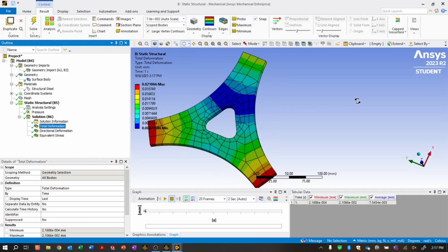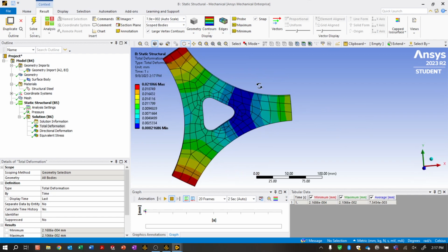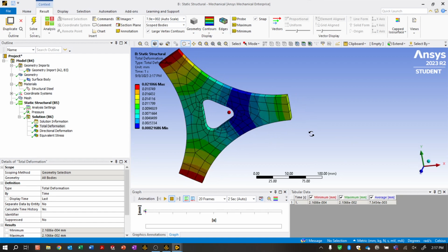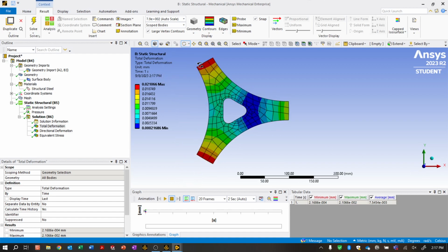And my total deformation, so it'd be in x and y. So that's how far these things have moved each way. And I would have expected that to be the same that way. But I do see that there's some sort of symmetry. Let me click this axis to make that look nice there, right? So if I take a slice of this direction, I basically get the same thing on top as I get down below. So that's the first bit of this tutorial.